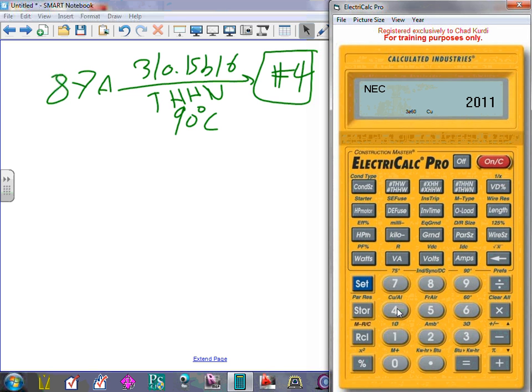What was our amp here? No, we're going to start with the 43 amps. I'm going to start with 43 amps and put the amps, right? Did I put my amps? Yep, I put my amps. Now, I need to change the ambient temperature. The first thing I need to do, change ambient temperature to what? To 60. Here's my 60, right? I'm going to set ambient, so I'm telling my calculator that my ambient temperature now is 60.